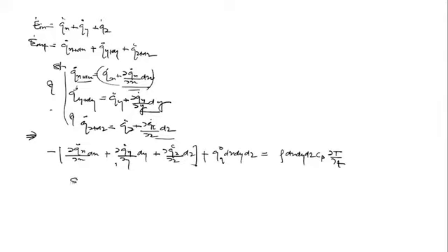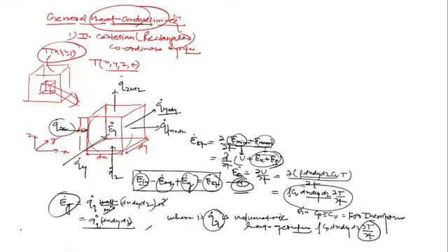And this is since, from Fourier's law, q dot x is minus k into dt upon dx, for an isotropic material, so kx will not be there. It's flux. I'm sorry, this should be capital Q, because it's the rate of heat transfer now.